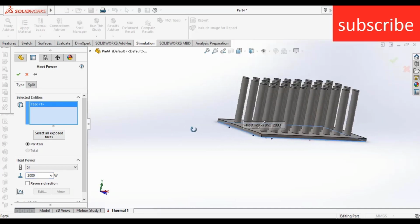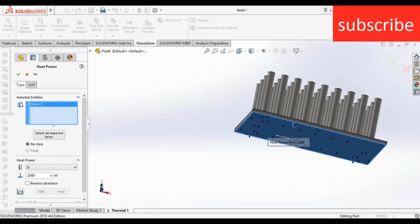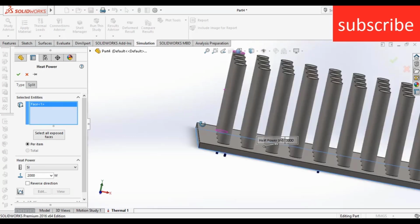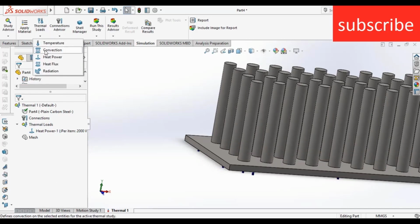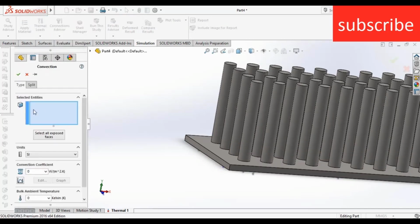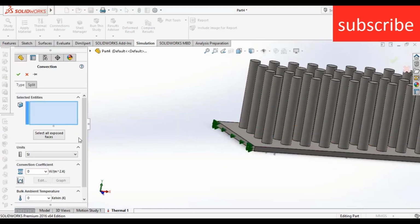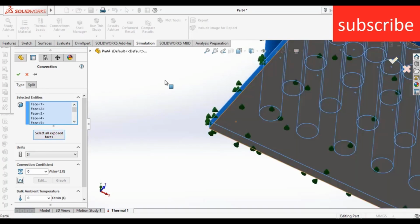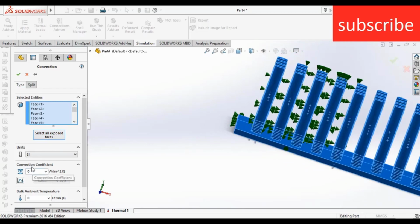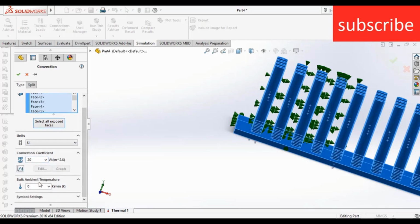I hope you all know about thermal heat transfer. So basically what I'm doing here is applying 2000 watt heat. Click OK and click on convection, and I'm going to try to cool this plate by air. Click on select all exposed faces and make sure you uncheck the bottom face. After that, go to convection coefficient, enter the value of 20 watt per meter square Kelvin. You can change the value as per your requirement.